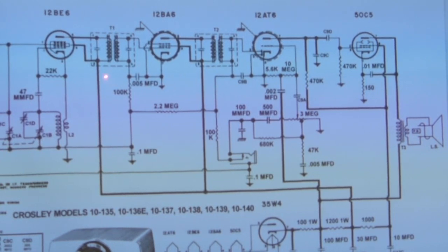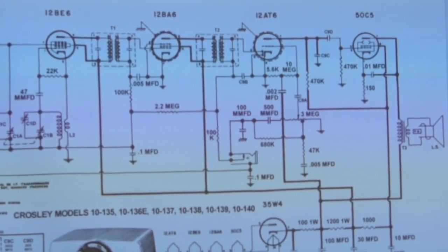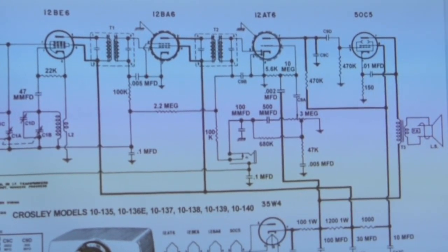All right, so I'm going to start with the assumption that we know that the power supply is working okay. You've measured the voltages here, and for an AC/DC radio, they could be up 120 volts or so. There's a dropping resistor here. These dark lines are all representing the B plus high voltage lines going to the radio. So it's nice to see that, and that sets it all apart from the other circuitry. All right, so we know that this is working.